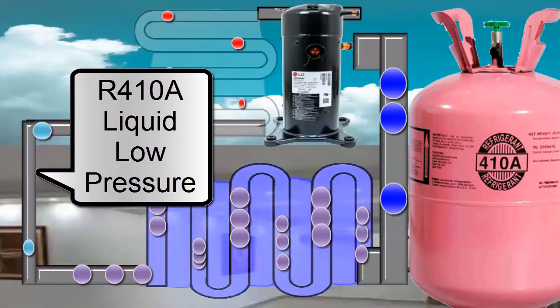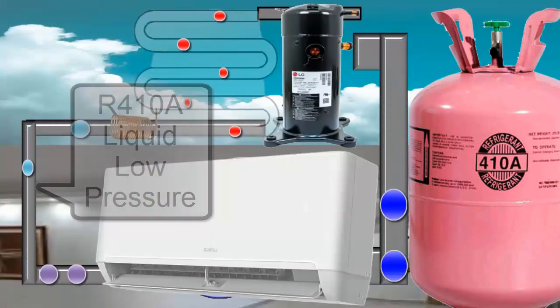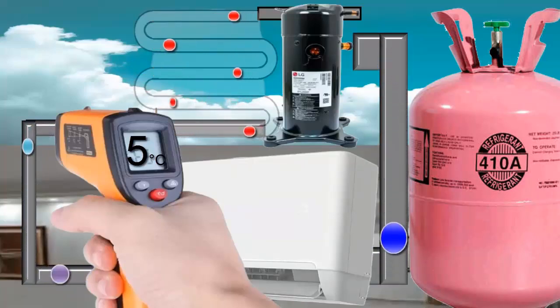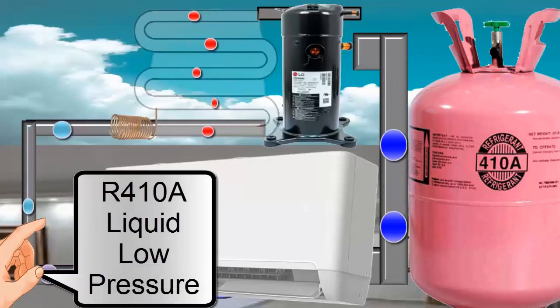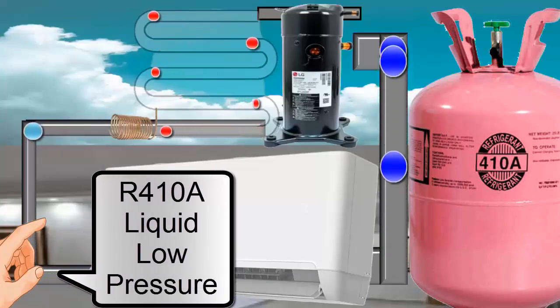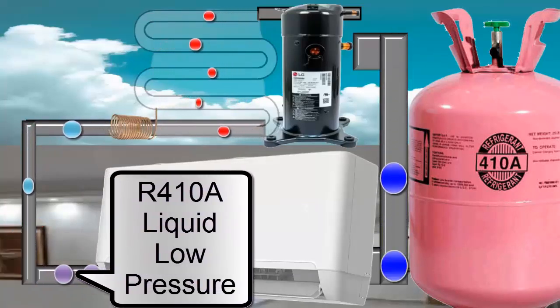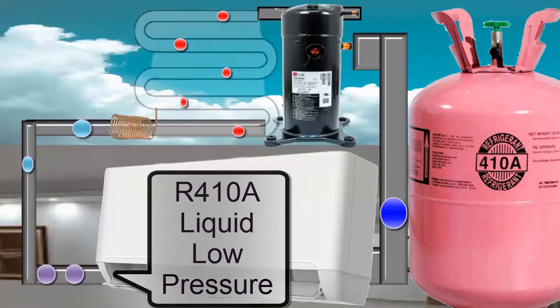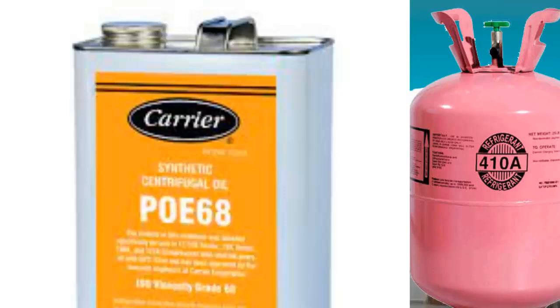The R410A gas is highly efficient, not flammable, but with the inconvenience of having a high global warming potential, close to 2088. Therefore, R410A is starting to face problems with environmental regulations. R410A works with POE-type oil, generally with a viscosity in air conditioning of 68 centistokes, although it depends on the compressor manufacturer.